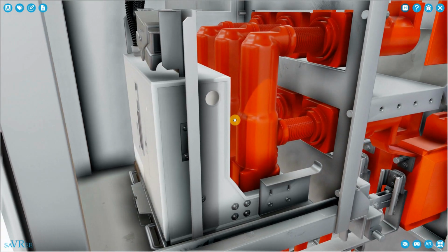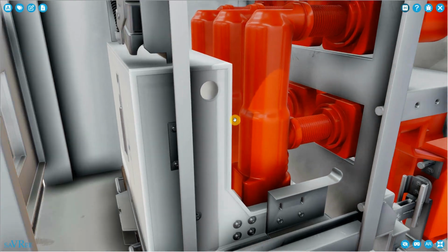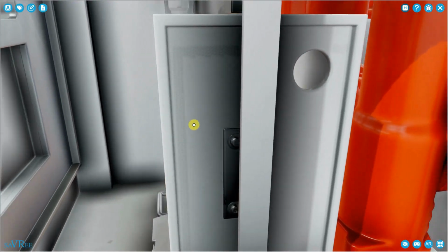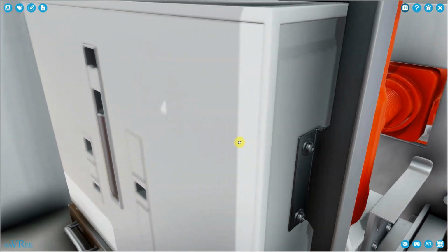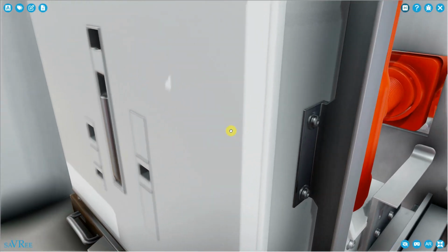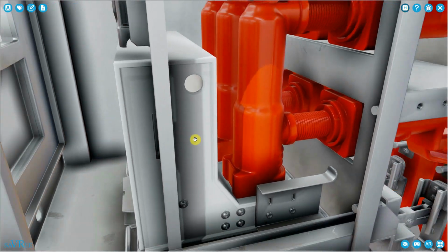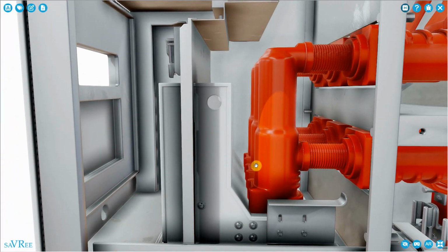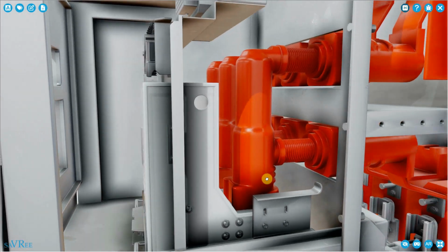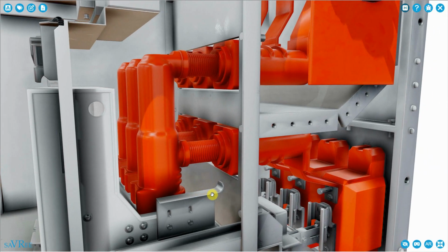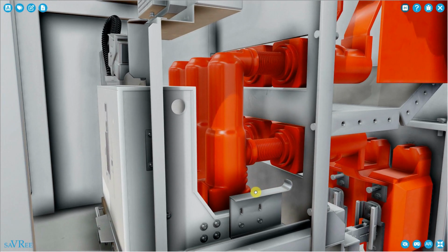When we want to remove the circuit breaker, we can do so quite easily. It's similar to the low voltage circuit breaker. It's modular in design. We just retract it. We pull it out from right to left. And as we do so, the earth switches change position also because they're interlocked with our circuit breaker.